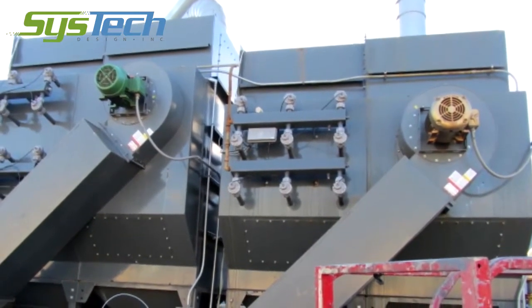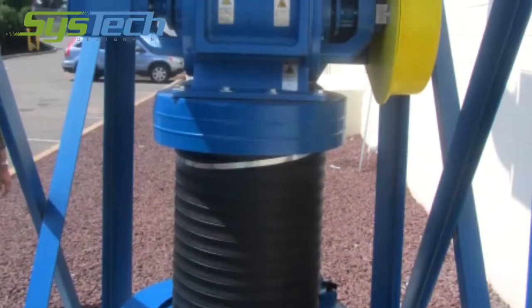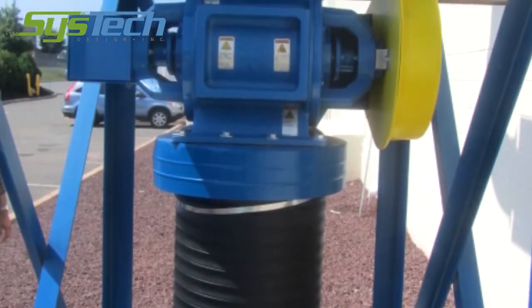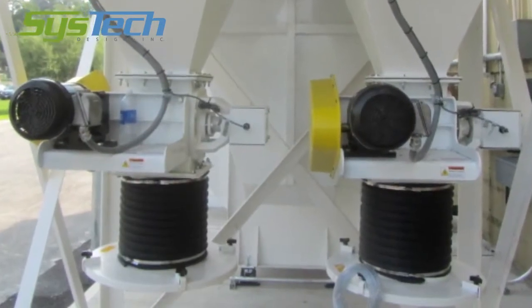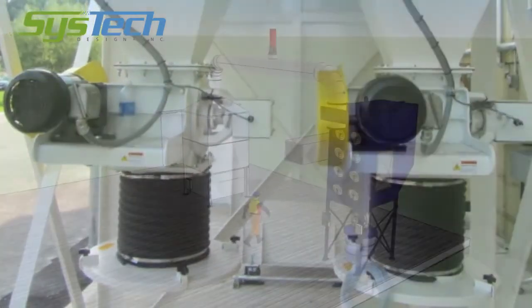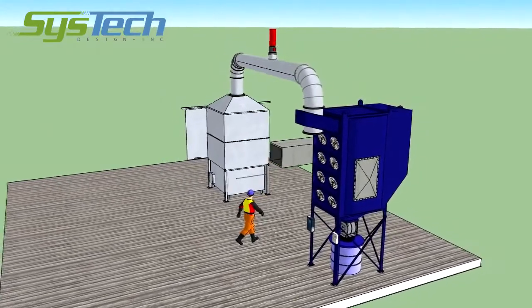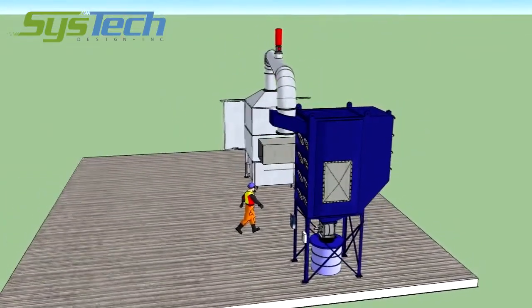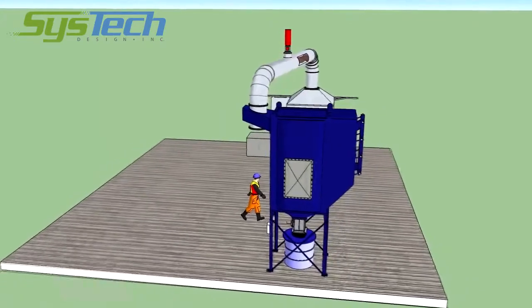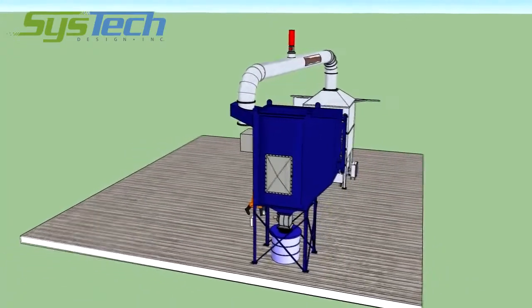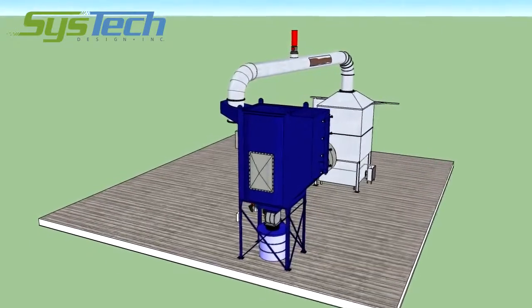However, given the fact that noise is logarithmically added, selecting a silencer with a design of 85 decibels might not meet plant mandates. For example, adding 2 noise sources with the same decibel value increases the combined decibels by 3, or in this case, 88 decibels. You need to be aware of other noise sources in the room or area along with reflective wall surfaces to ensure the entire space remains compliant with OSHA regulations.